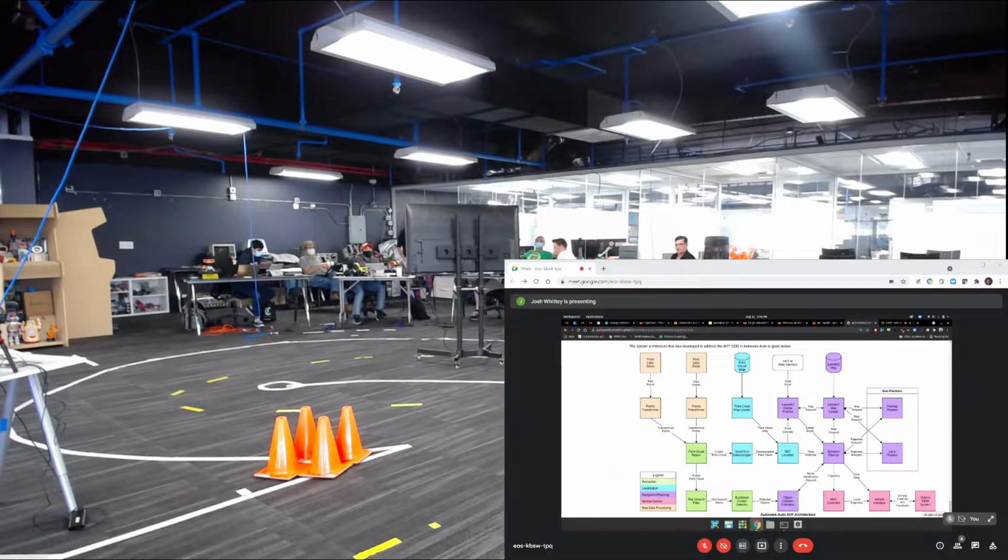And the way it would plan among all of the lanes and the other parking spots and stuff is using a Lanelet2 semantic map. Lanelet2 has an API where you can say, this is my current geolocation, this is my goal geolocation. Now using the network that's defined in this roadmap, figure out all the segments I need to go through to get from A to B. And so that's basically what the global planner does. It gives you a list of segments that you need to drive through on the map.